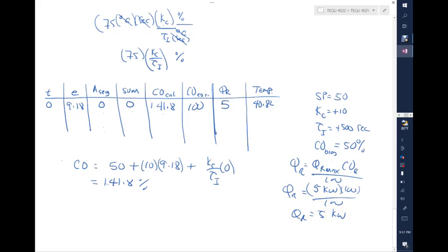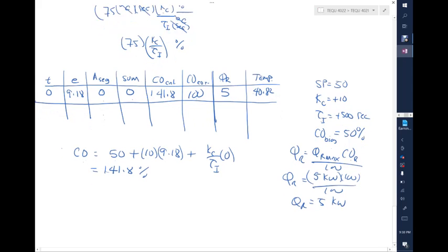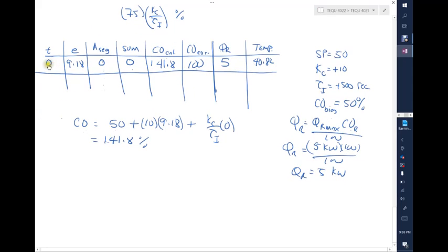So it means that since we are trying to increase the temperature to a set point of 50, but we are at 40.82, the system is just increasing the value of the watts that we are supplying to the vessel to the maximum of 5. But that's just the first line. There's nothing else to do. What's going to be the second line? The second line is, as soon as you increase the time to 10, you got to calculate what's the new temperature here. That new temperature is based on the model.